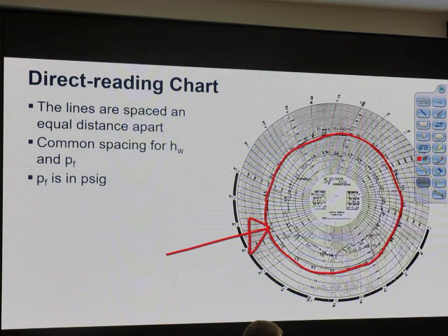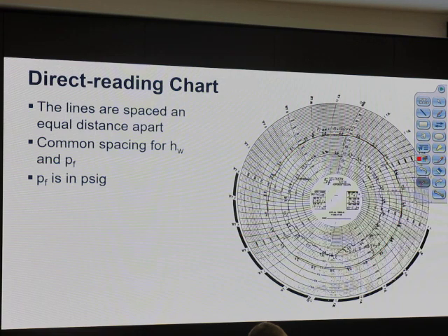What's your name, sir? James, what do you think? Choice A, P sub F. Choice B, HW. What is that line, James? HW. Okay, next. What's your name, sir? Anderson? P sub F or HW? Pressure. Very good, correct. When you see it's more or less constant, that is the pressure in the line. The pressure in the line, whether we have flow or not, stays more or less the same. But the pressure drop across the orifice plate fluctuates, because sometimes we may not have any flow.